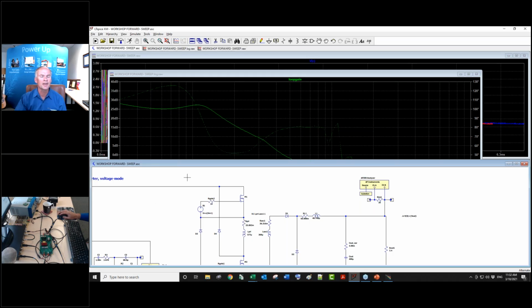Now, one thing I might expect to happen, by the way, if we imported this loop prediction from LT, is that it might have a closer Q than the models because it's going to have the ripple on the op amp. So the things missing from the modeling will be present in the LTspice simulation, and the simulation will be better than the small signal model. How about that, huh? You don't expect that normally. Well, it's a simulation, so it's not going to be as good, but it actually will include effects that the modeling doesn't include.